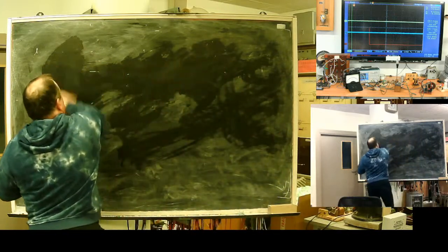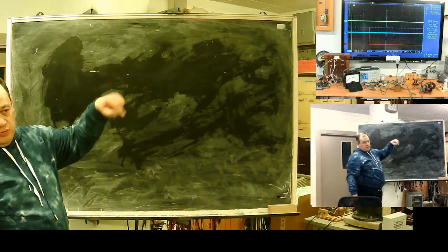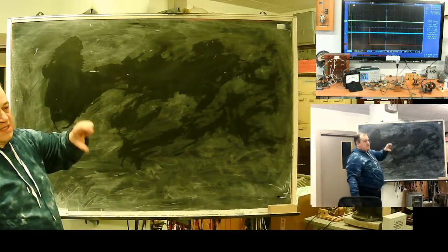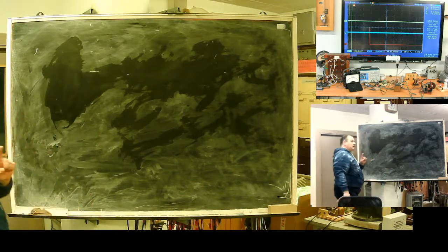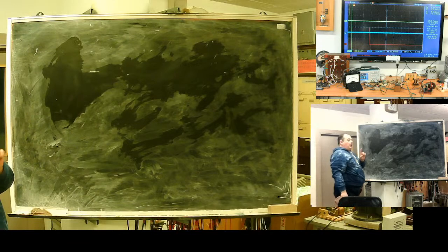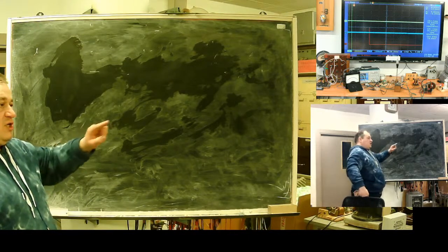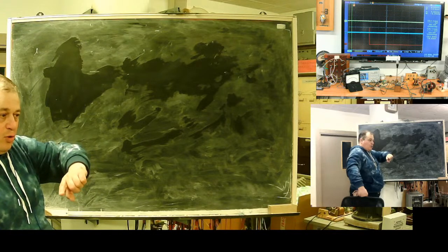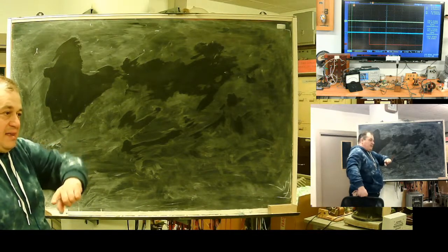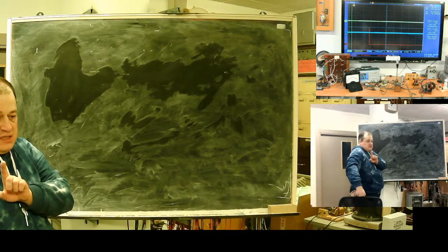In an ordinary network, they go down with amplitude. In an ordinary network, the highest is the third, then the fifth, and it goes down. But ordinary network means no power converters. With power converters, the situation is first decaying normal, or let's say old-style harmonics, and then there can be peaks from converters.